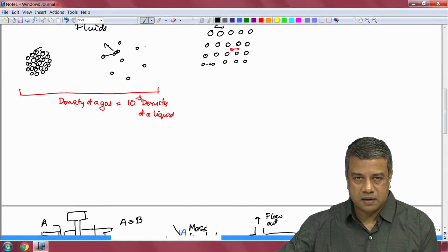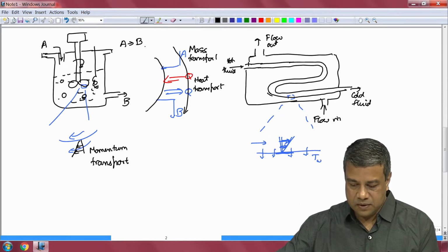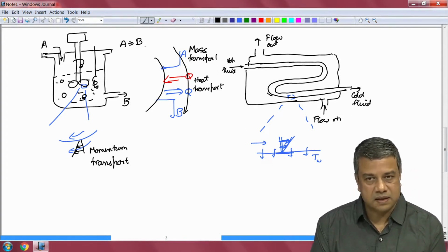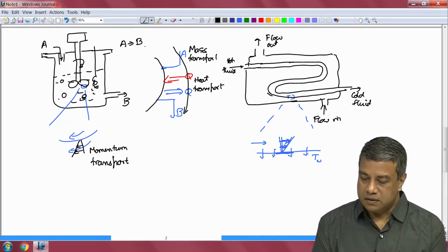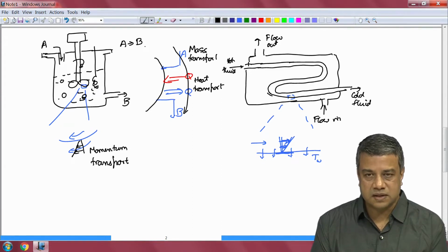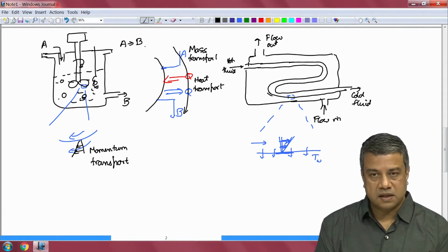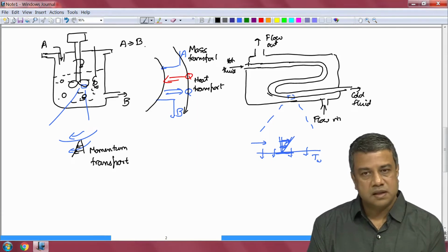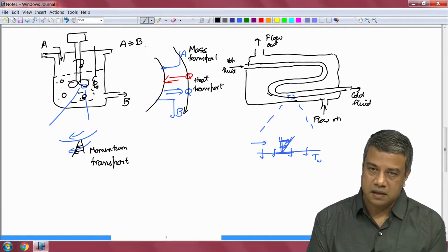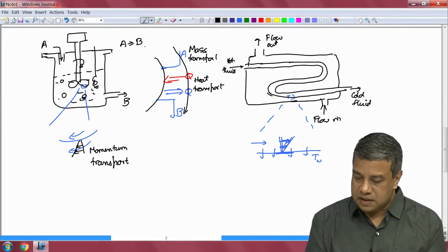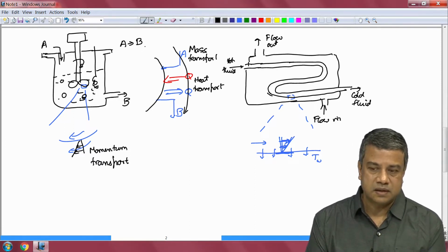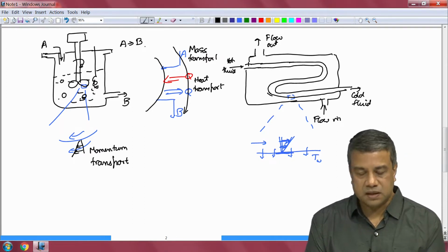Okay. So, here we shall look at transformations in fluids, and I had explained to you why we need to look at transformations. So, we took the example of a stirred tank reactor, where a reaction takes place at a catalyst surface. You pump in the reactant, you pump out the product, and you provide sufficient heat for the transformation to take place. That is not enough. You need to make sure that there is sufficient transport of reactant to the surface of the catalyst where the reaction is taking place, sufficient transport of product from the surface where the reaction is taking place, sufficient transport of heat to the surface in case of endothermic reactions, or sufficient transport of heat from the surface of exothermic reactions. And all of these transport rates are related to the variations in properties between the surface and the bulk. The mass transport is related to variations in concentration, heat transport to variations in temperature.